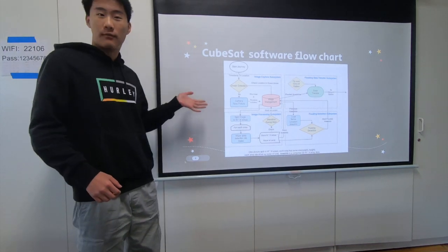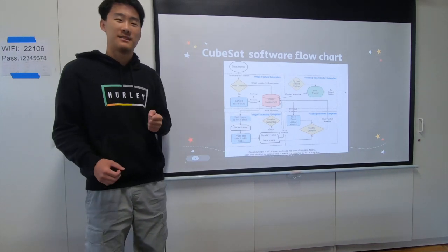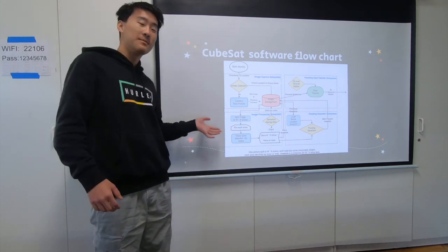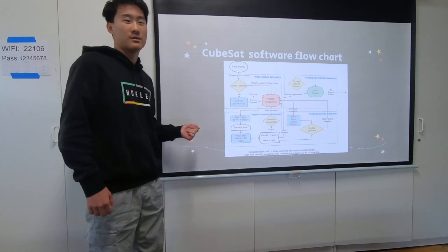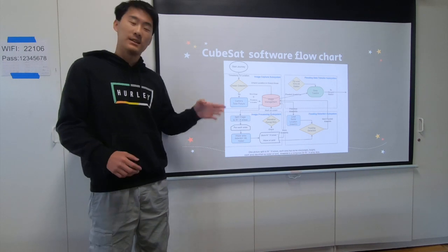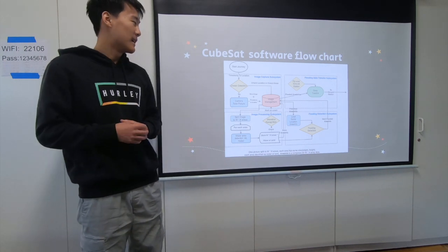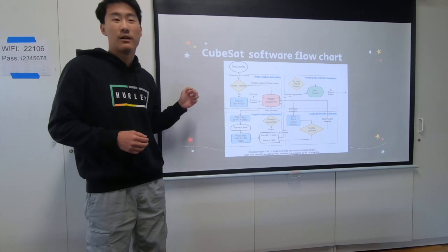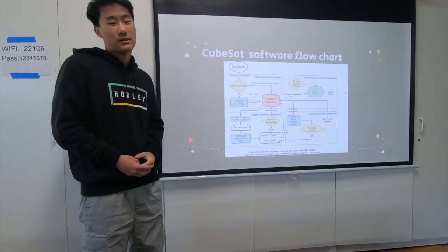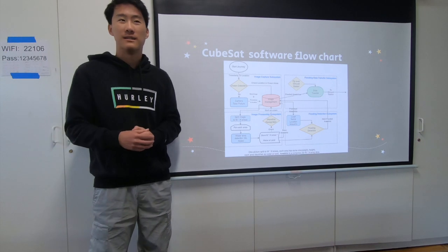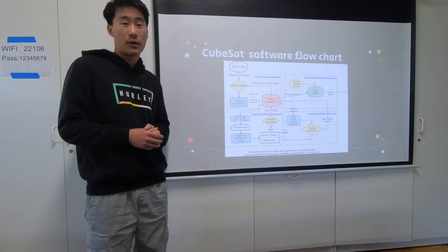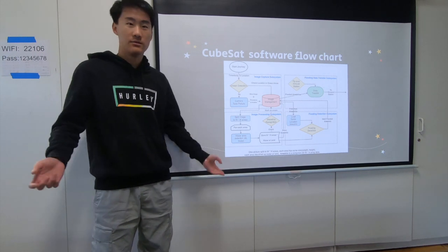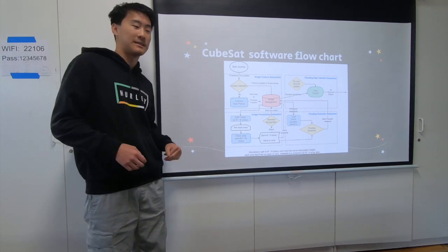and this is our software flowchart. I'm going to be discussing how our software works and how it integrates with everything in the subsystems. Our journey starts with our CubeSat moving to a specific spot on planet Earth, and we take a timestamp of that location and then run our ocean detection model. Why we need to do this is because we don't want to photograph places that are just ocean, because that's kind of useless. That is not the point of our CubeSats.